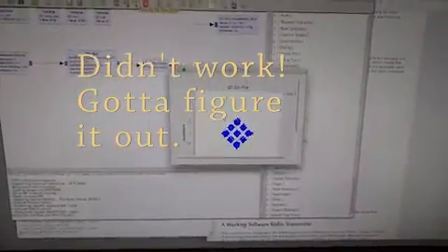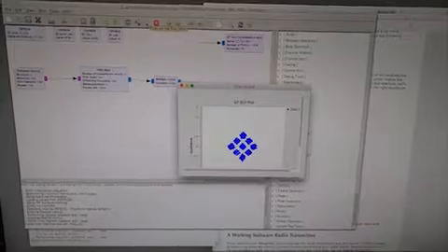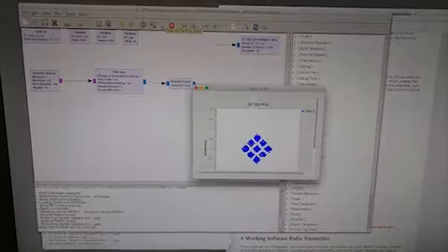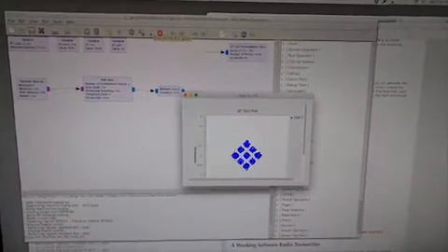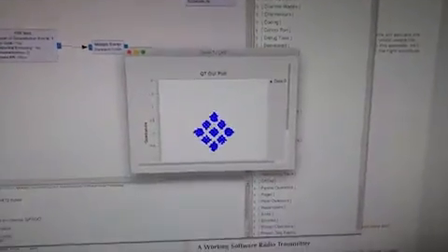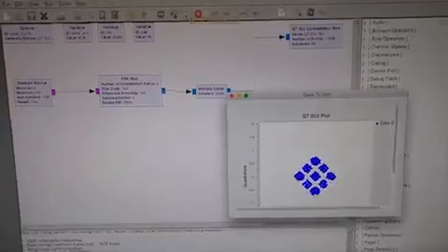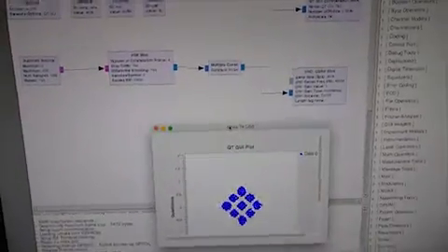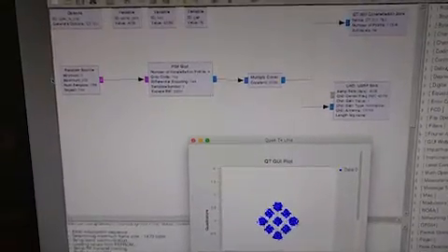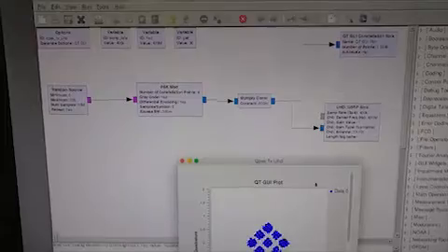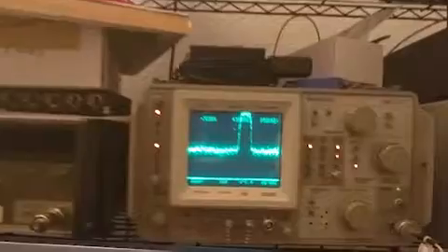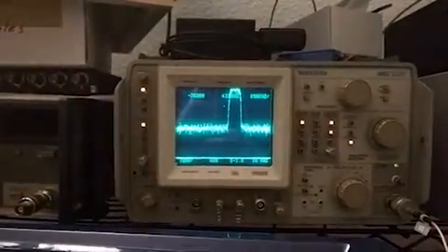All right. Take 47. Welcome to GNU Radio 101. We downloaded a QPSK example, or PSK example. They set it up to where it was doing this. Here's the constellation. There's our flow graph with a sink, and multiply, and PSK modulator, random source. Up here is a constellation sink, which gives us this handy thing. And guess what? It's transmitting. Okay, so step in the right direction.